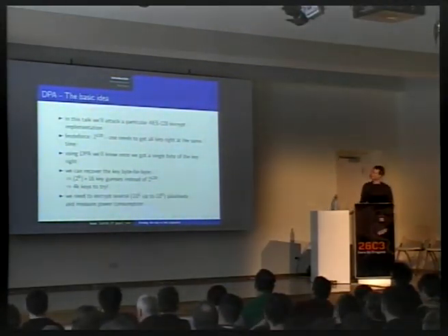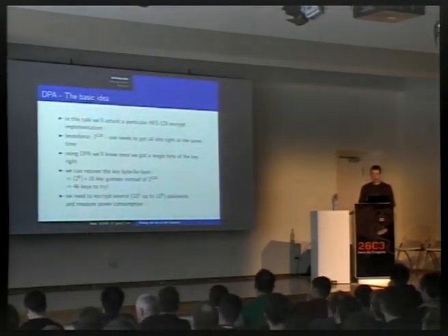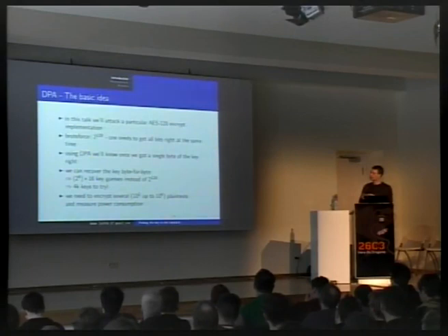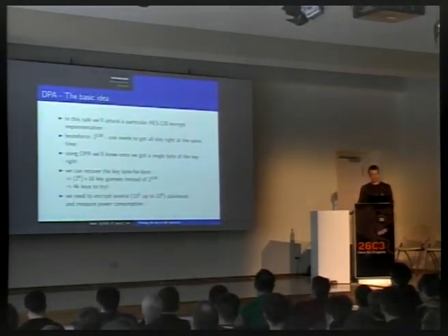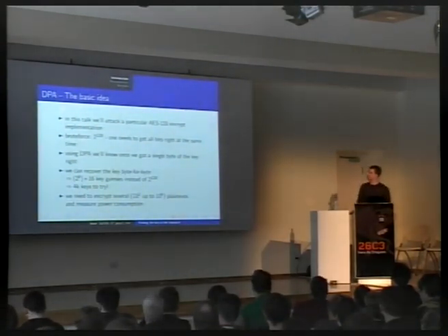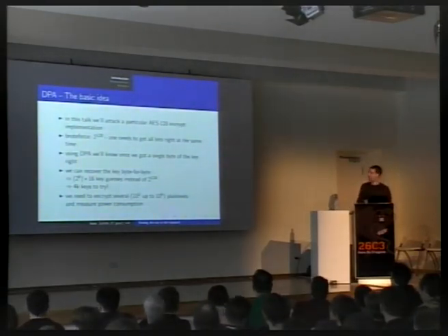But to do this, we need to encrypt several plain texts and measure the current consumption during this encryption. This is in the range of about 100, up to a few millions is also possible. It depends on your measurement setup, on the noise, and on countermeasures and whatever. But in our example, a few hundreds will be sufficient.